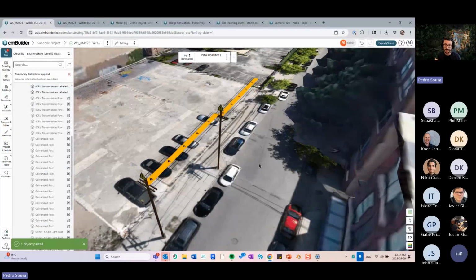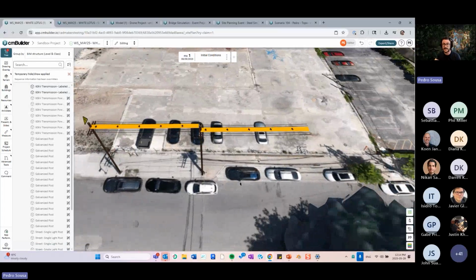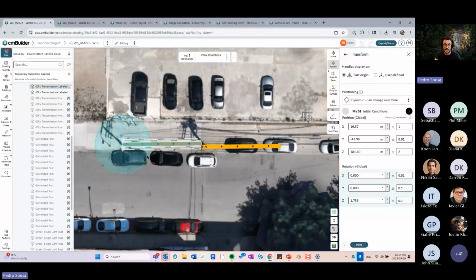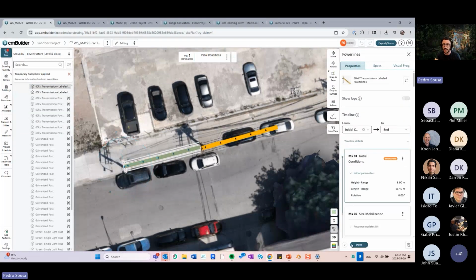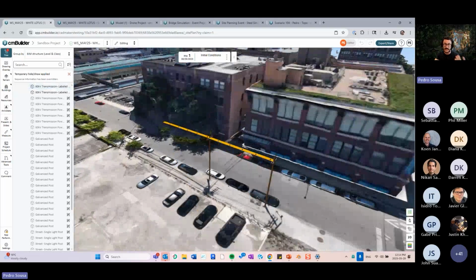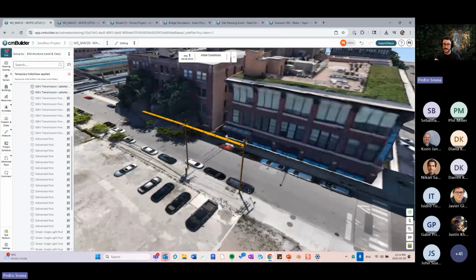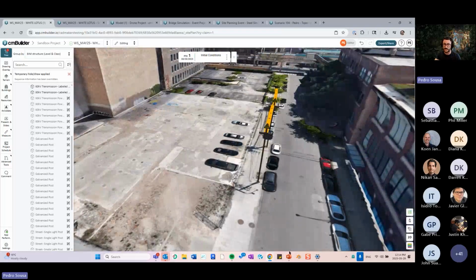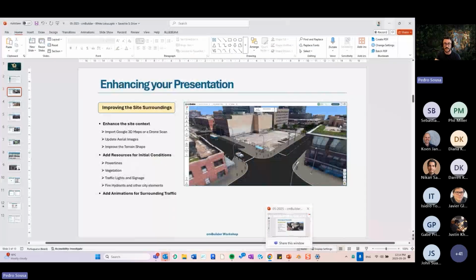Inside the same area. Okay, and then you can spend a couple minutes just redoing this shape and representing the items that will really impact your planning, to make sure that you get them all correctly done over there, because this will impact, for example, crane access, other vehicle accesses, and so forth. Okay, so other things that you can do: power lines, vegetation, traffic lines.